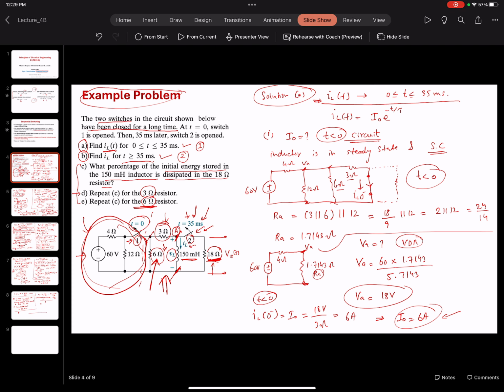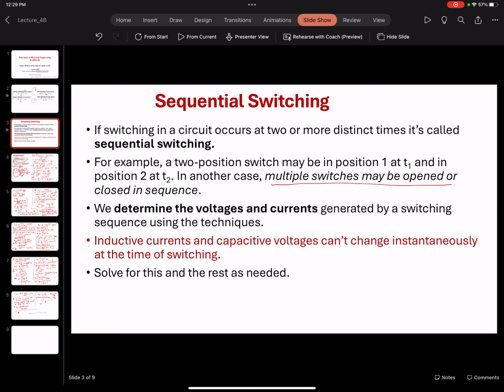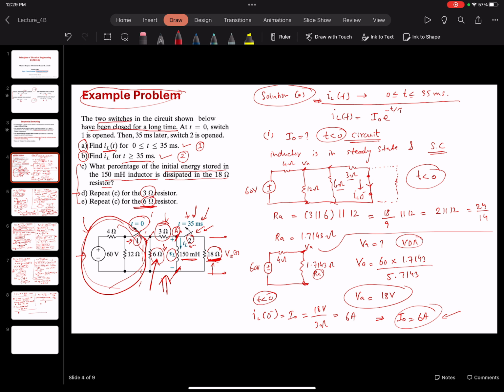You should know that after a switching event, what is the circuit that is remaining, how to find equivalent resistances to find the time constant, understanding that, again, this point is going to be super helpful while doing all of this initial voltages calculation in RC circuits and initial current calculations in RL circuits, because of the open circuit and the short circuit equivalencies that we usually establish.